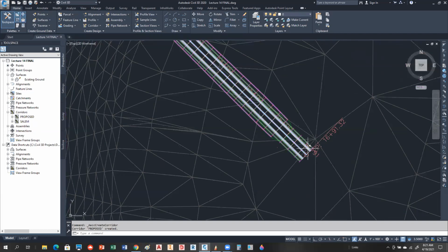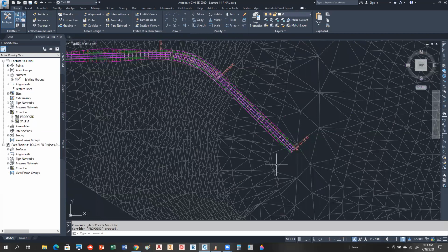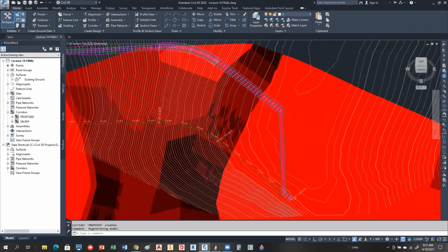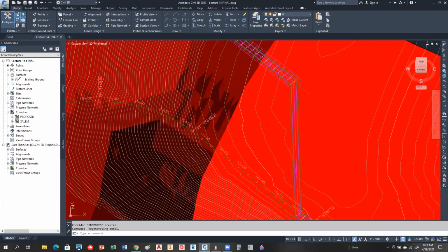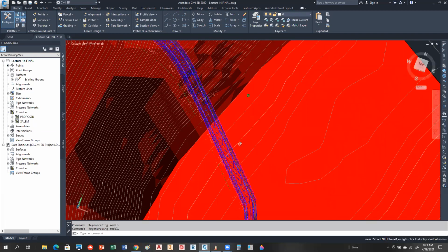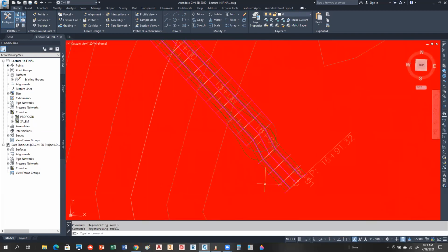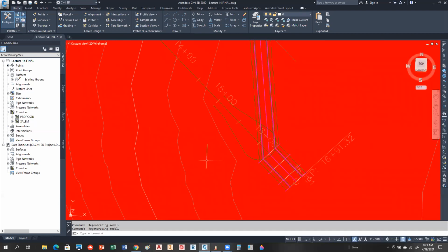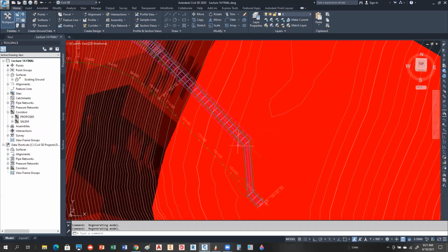And out here, we got a problem. You guys don't need to do this, but I want to show you what's going on here. If I zoom out of this, do you notice what's happening with my corridor there? It's kind of hard to see, but can you see what's going on? It's just dropping off. That's called a waterfall, and you can see why it looks like a waterfall. That's a problem. The reason there's nothing happening there is there's no profile over here, so it doesn't know what to do with it. So it just drops it off to 0, okay?